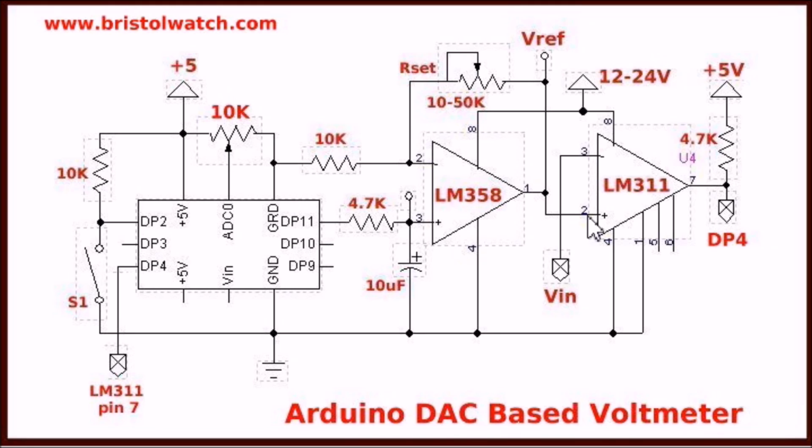Sooner or later, it's going to switch either high or low, pin 7, and when it detects that, the pin 7 state change on the LM311 is read back through digital pin 4. The Arduino automatically knows, hey, this count gave me this voltage, and you multiply it by whatever it was, and you can get a voltage reading.